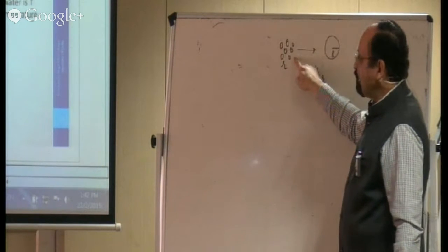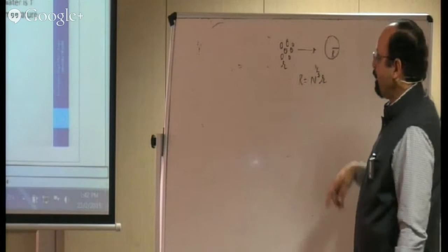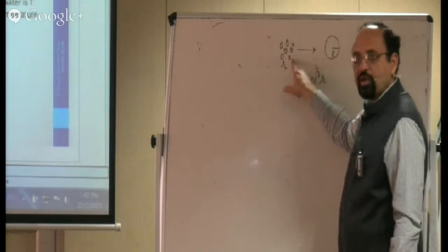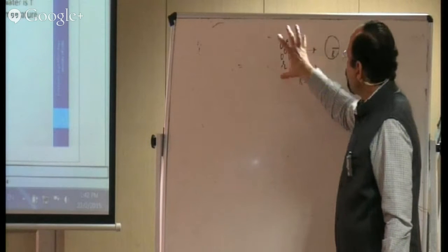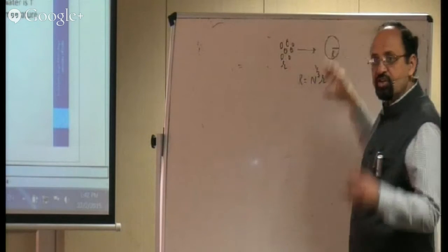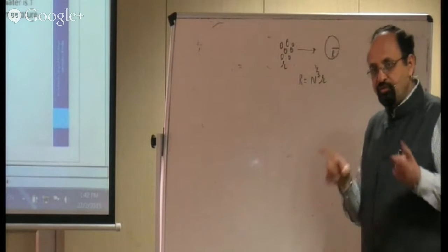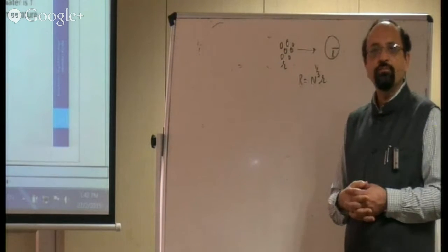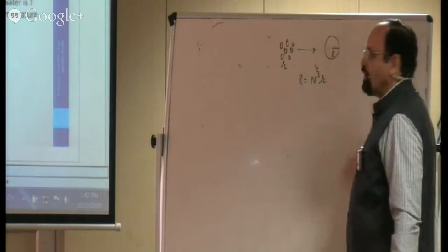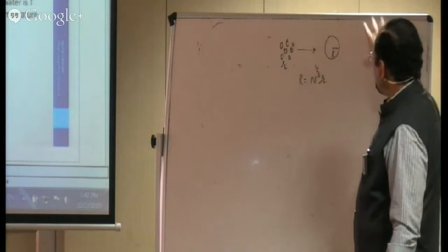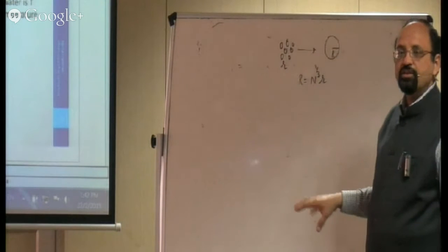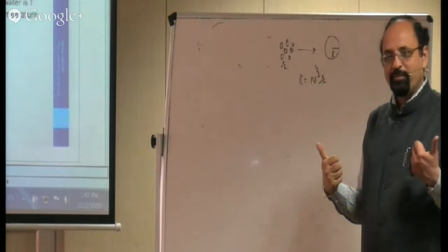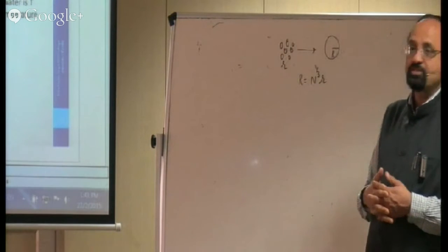From the point of view of surface tension, because T is given here, you can easily understand that he is talking about the surface energy. So from this stage to this stage, there is a reduction in the surface area. Henceforth, there is a reduction in the surface energy. Where is this surface energy going? If there is no possibility for the surroundings to take this energy, the body itself will make use of this energy to increase its temperature. So this is something what must have happened.